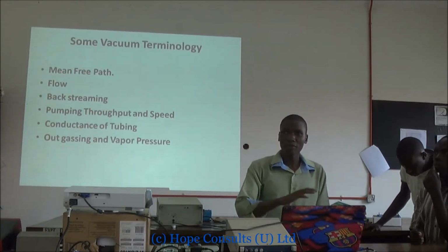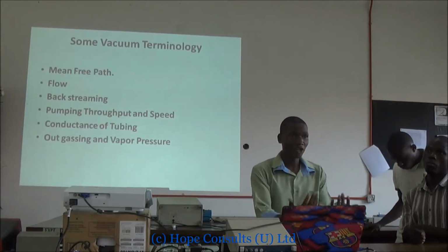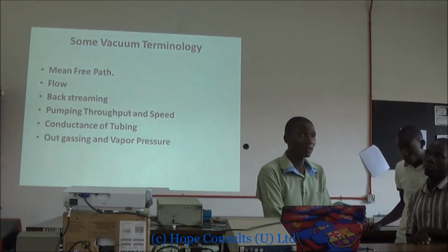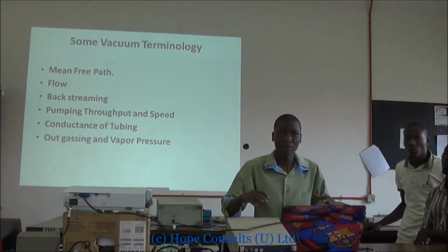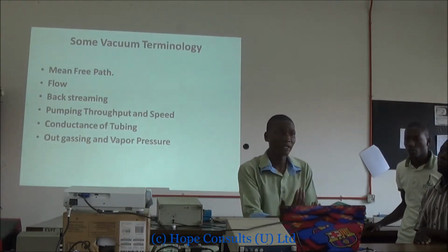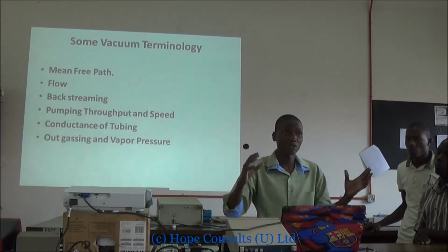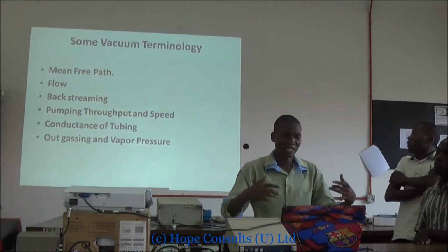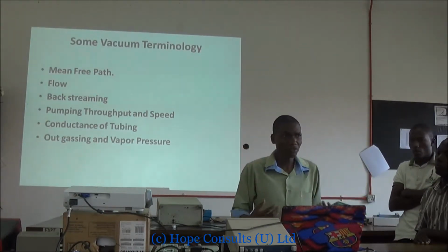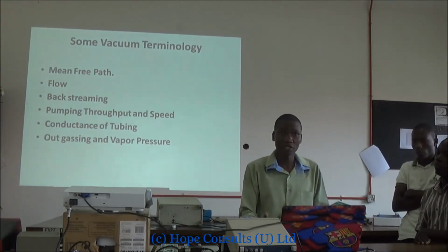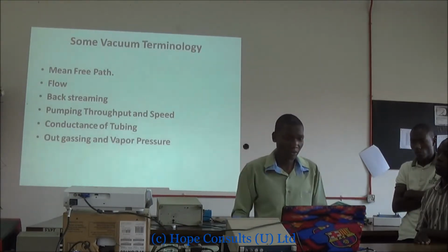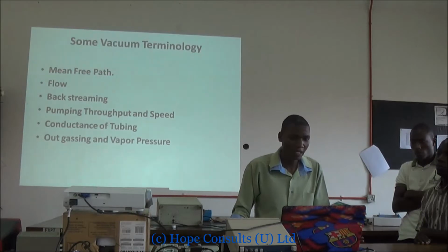As you try to pump, sometimes not all molecules will be forced away. So as you try to create a vacuum, some molecules will tend to flow back as you press the piston and flow back into your vacuum. That's what we call backstreaming. As you create a vacuum, some molecules tend to come back into the system. That's backstreaming.